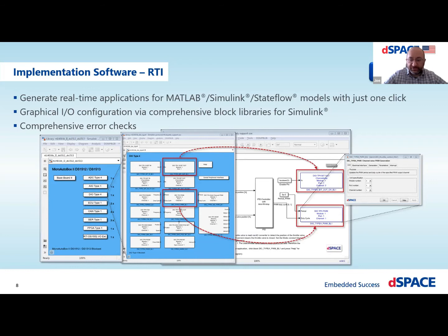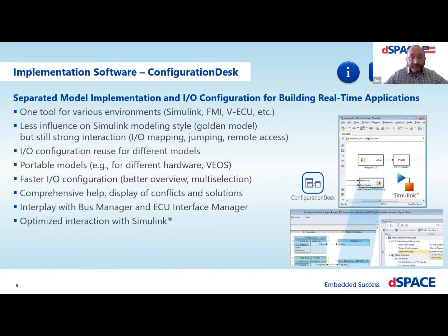It is changing a little bit into the future, and then here's the next slide, our future, and it's actually really our current interface called Configuration Desk. So now instead of actually instrumenting your model, what we're having you do is basically import your Simulink model into a tool called Configuration Desk, and then the I/O interfacing is done there. Now, one of the big advantages of that is that your Simulink can remain completely neutral on the dSPACE environment, so that when you want to use them later on, for instance, for production coding and passing them on to other users, you don't really need to worry about the dSPACE instrumentation. It's all done here through Configuration Desk.